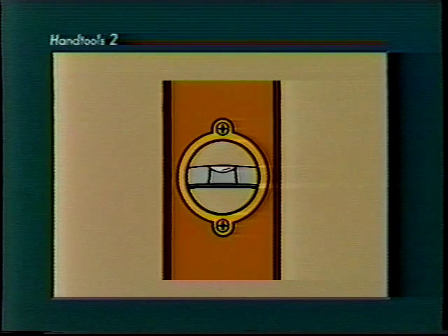If the level is not exactly plumb or level, the bubble will move away from the center, indicating the position is out of true vertical or horizontal position. The vertical bubbles are positioned 90 degrees from the horizontal. Use the vertical bubble to align an object when checking for plumb.